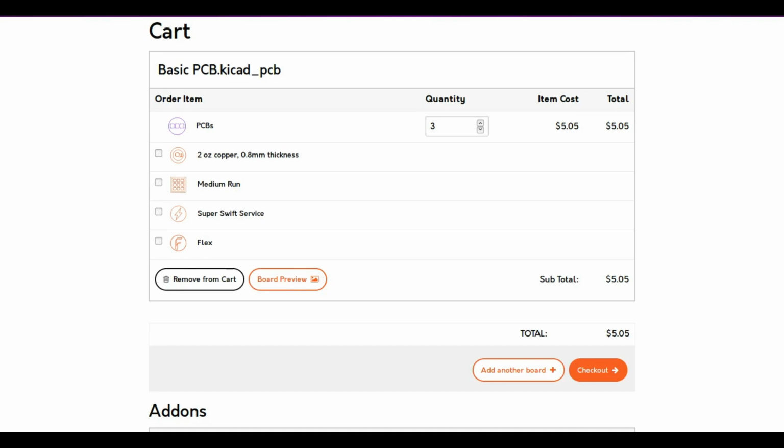because I was calling this kind of like the preliminary lab to the actual lab, but the actual lab was really the same thing with like a voltage regulator on it. And you can already see that the 1 inch by 1 inch spacing here is really not going to be, we can't get a voltage regulator in here along with all this surface mount components. So I think we'll do this, call this one done. The next one will be a bit more complicated. And we'll definitely be moving on into surface mount components and call through hole essentially done unless we need it for certain other components that require it, like your MOSFETs and such.